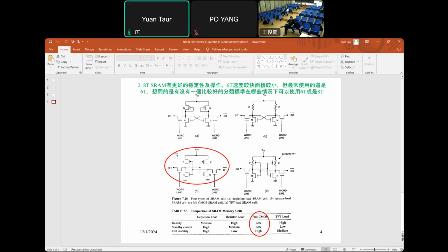So usually when people go to 6T, we achieve the cell stability compared with the others, and there's no need to go to 8T. It's only for special applications they go to 8T. Actually, it's not just 6T and 8T. If you look through the publications, there's 7T, and then there's even 9T. Okay, so 8T is not unique in that sense.